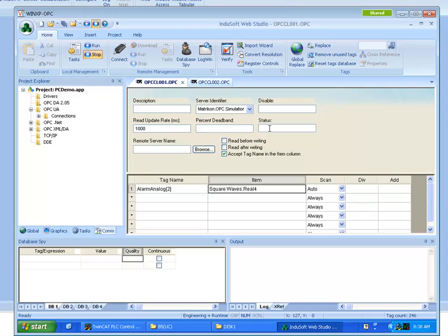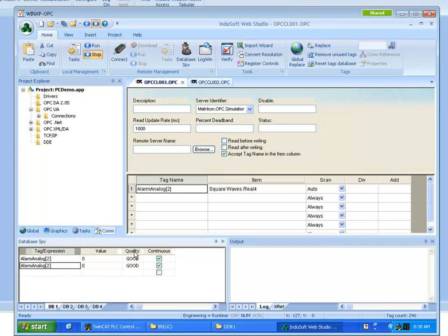And you can have here a tag that will receive the status of the link with the server. So the status, basically every 5 seconds, we call the get status from the OPC server. If the server is fine, we receive the value 1 on this tag here. Otherwise, we receive an error from the server. And I'm going to show here on our debugging tool when we have a tag, here I'll have the value, but we also have this field called quality, which I can access in my application anywhere if I just type the dash greater than quality.